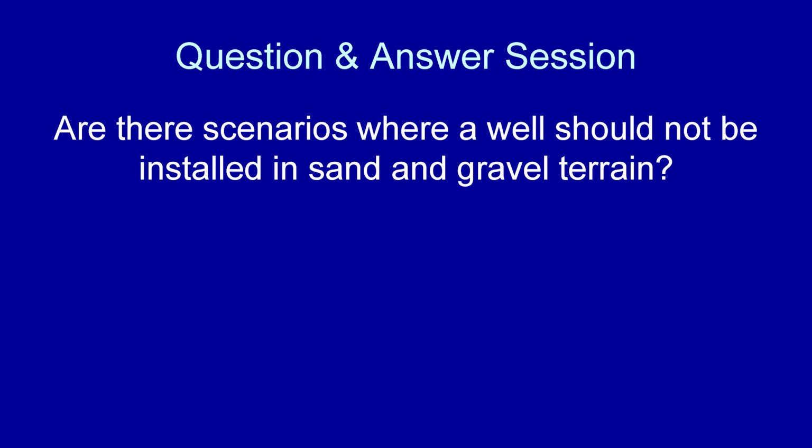Example, if your sand and gravel deposit overlies a major fault, it is possible that pollution can move as much as a couple of miles away, so that you have to be very knowledgeable of what is going on. Most people do not think that sand and gravel deposits derive recharge from the underlying bedrock. That is incorrect. There is a distinct relationship between the overburden and the underlying bedrock.